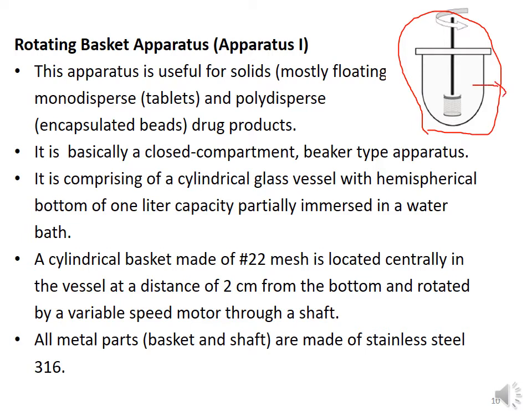It comprises a cylindrical glass vessel with a hemispherical bottom of 1 liter capacity, partially immersed in a water bath. This is a beaker, with a hemispherical bottom and 1 liter capacity. A cylindrical basket is made of number 22 mesh. This is the size of the mesh.